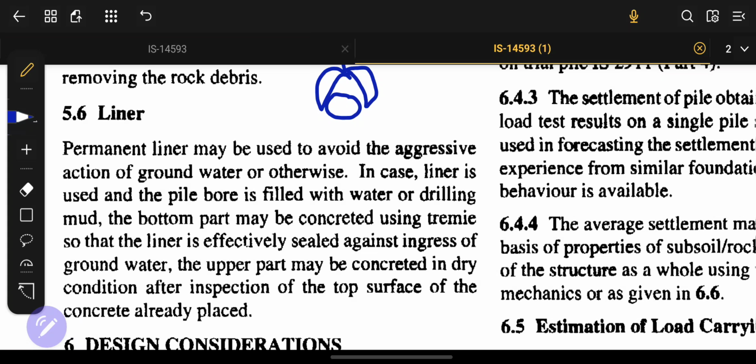If it is set, the gel formation in the pores has taken place, then there is no problem. We can later remove the liners, and we can keep the concrete exposed to this thing, because we have designed our concrete for that kind of exposure.